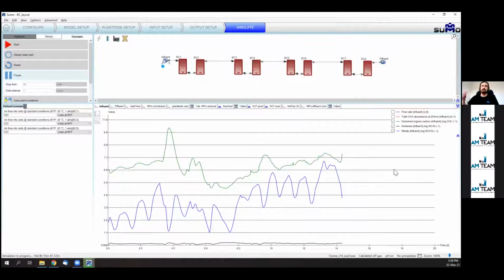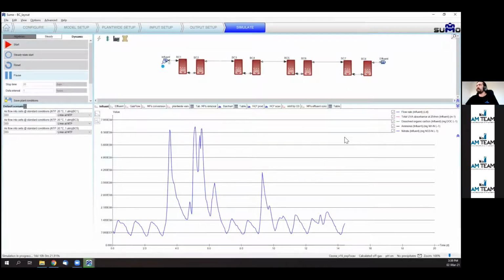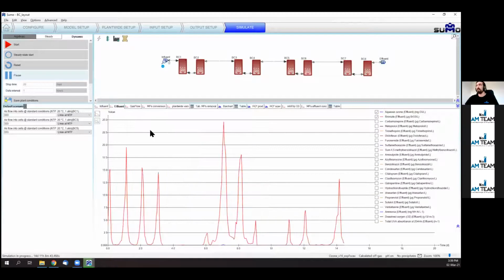So every one of these variables will have an impact on your final bromate formation and also on the micropollutants removal. And as details are important, all of these variables will affect both the ozone lifetime, so the ozone residual in the installation, and will also ultimately affect the lifetime of radicals, because changing the water strength with the rain events, you can get dilution.